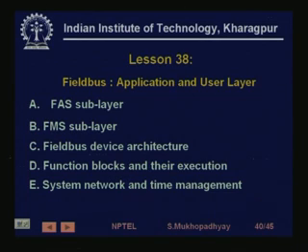So, when one device looks at another device, how does it come to know how that device is made, what it is doing, and the interpretation of the variables that one device is sending to the other? All these issues are dealt with at the application and the user layers, and we mainly discussed the function blocks, which are the abstract model for any field bus device. We also discussed the issue of obtaining synchronization throughout the network, that is, doing network management and time management over the network.